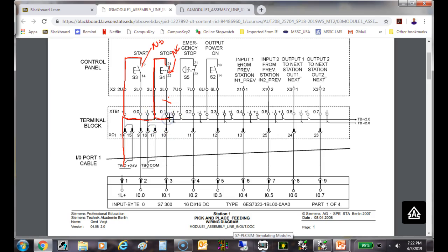So these guys are hooked up to source, right? You understand that? They're all using a positive common. Are we okay? So that means the PLC has to be considered to do what? So the PLC has to be sinking, because the inputs are sourced. You understand those terms? So that means if I buy a sensor for this PLC, it's got to be a sourcing sensor.